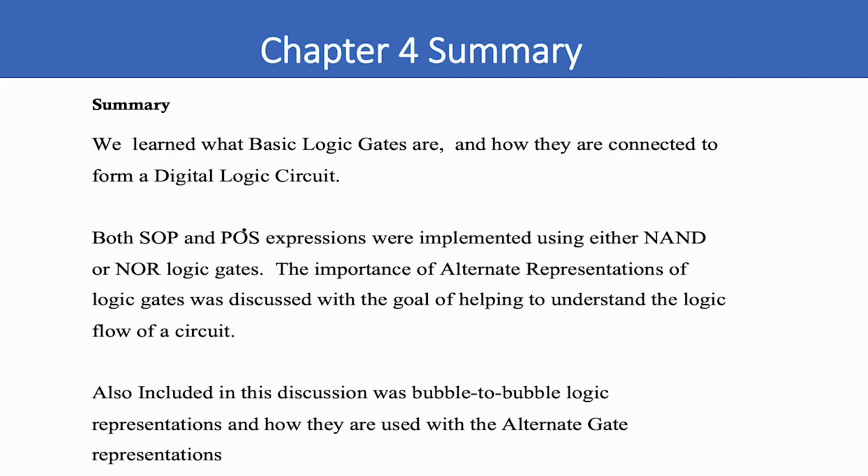And we saw the importance of alternate representation of logic gates, because in order to understand the circuit that we've designed or somebody else has designed, if you use the alternate representation that displays the actual circuit flow of the logic that you designed, it makes it so much easier to understand what's going on, especially when you're troubleshooting a logic design, trying to make sure that the gates are connected correctly, or you have a flaw in your logic design, whatever problem that you might have.